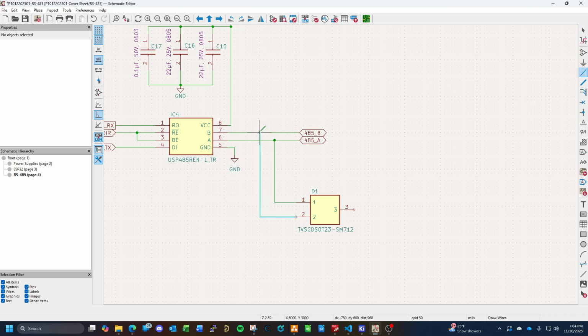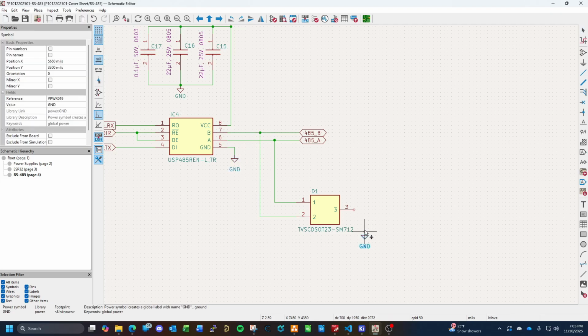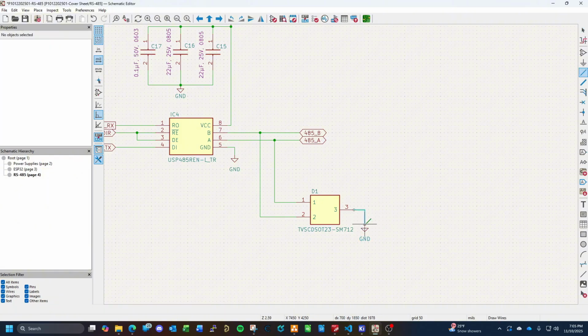Snag onto these guys, and throw this guy right here. That way, if you accidentally walk across the carpet and touch these two lines, the ESD discharge would be less likely to hurt this guy. It'll go through this diode and be passed safely.